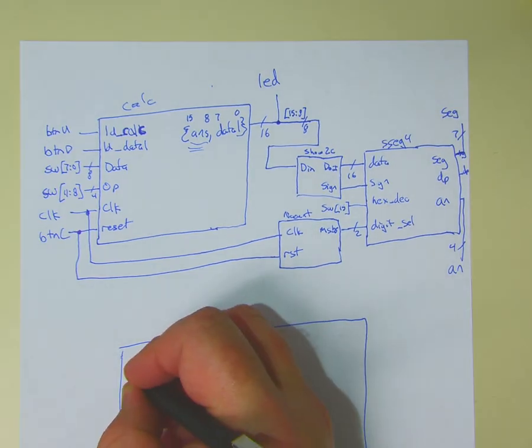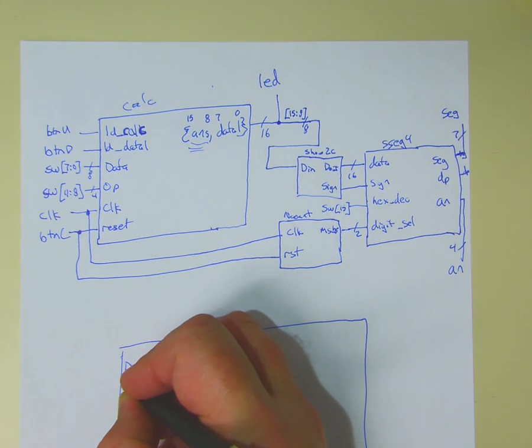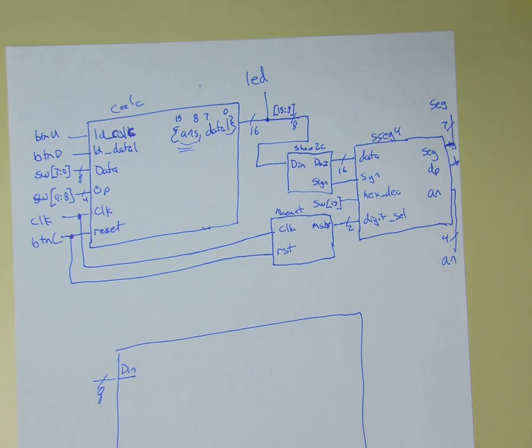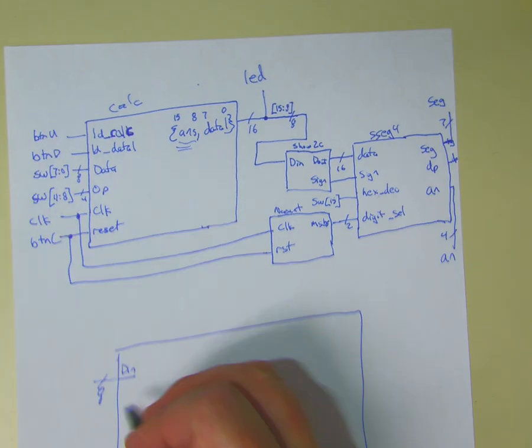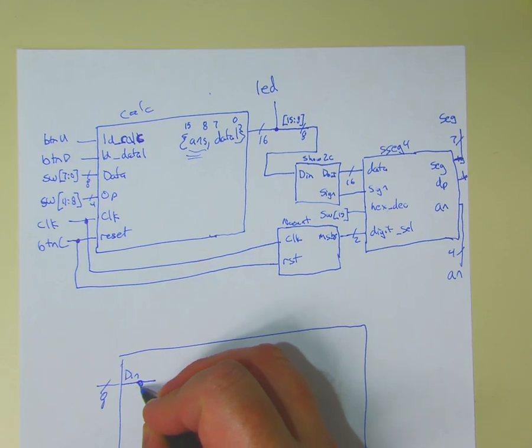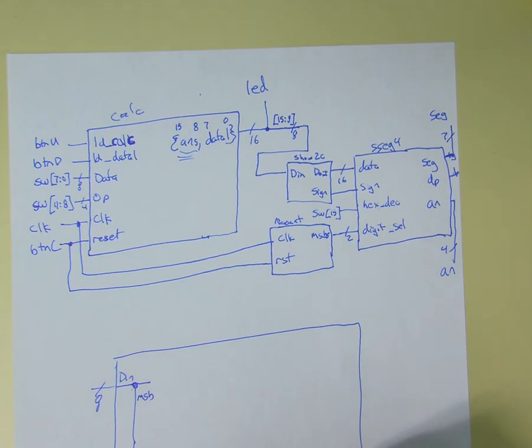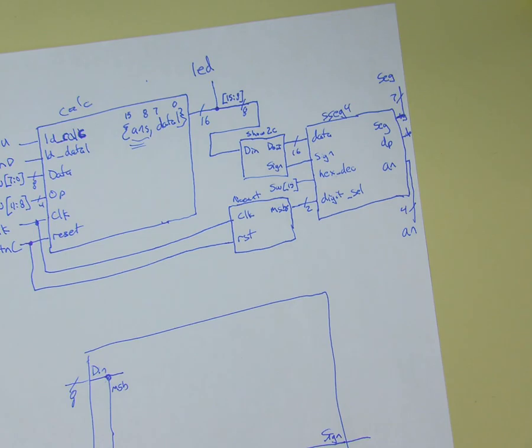So we're going to draw kind of a big picture. Data in. And it's 8 bits. If I have an 8-bit number, and I assume it's in 2's complement, how do I know if it's positive or negative? First value is 1. Yeah, I look only at the first bit. Does that make sense? So I can grab from here the most significant bit and I can run that immediately out to the sign bit. That's all I need to do.